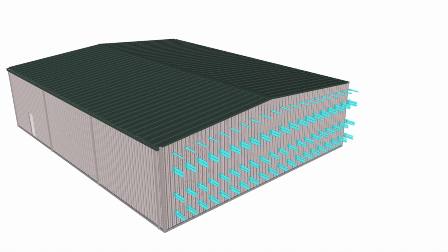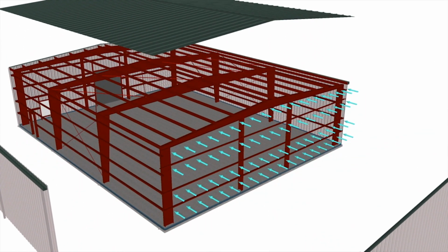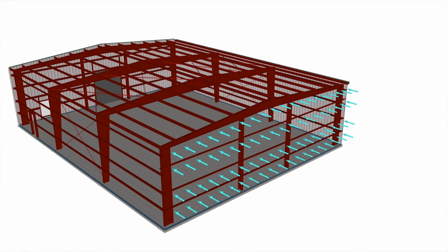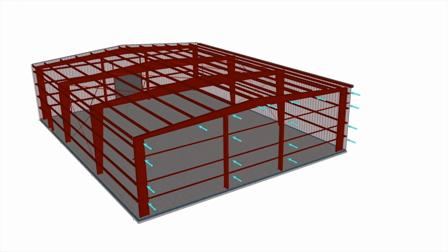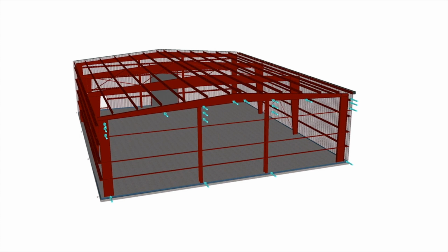The wind pressure is transmitted from the end wall cladding to the horizontal girts and rake beam at the top. The wind load is then carried by the girts to the columns and end posts. The load on the rake beam is transmitted to the support points at the strut purlins.